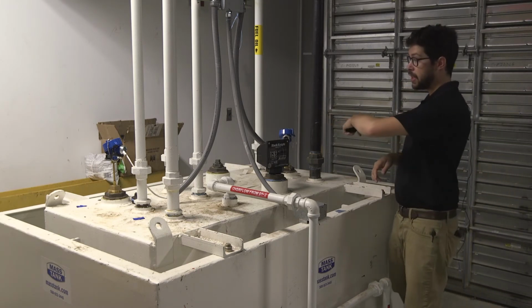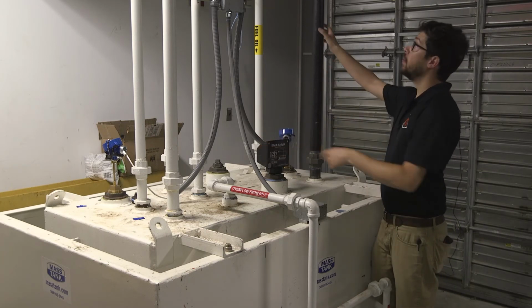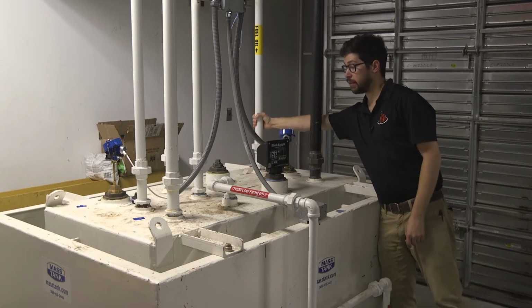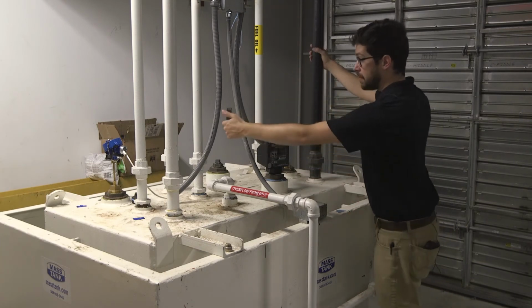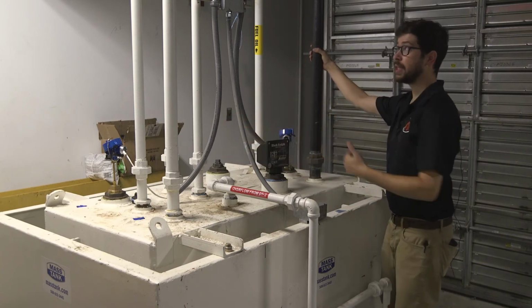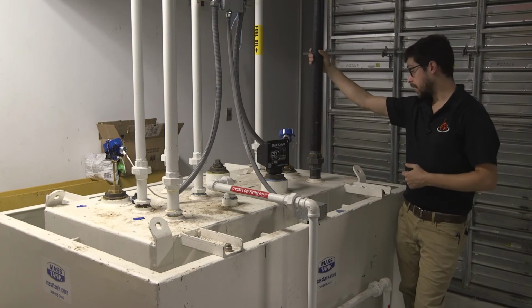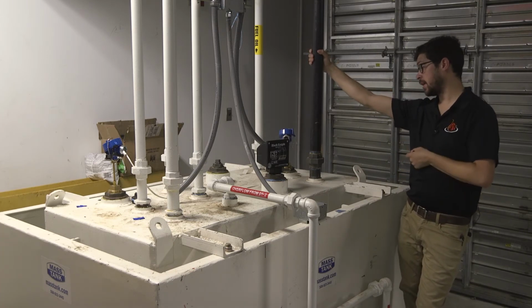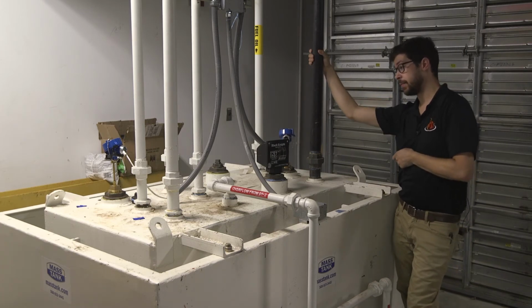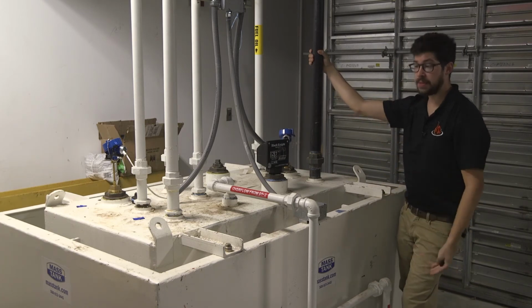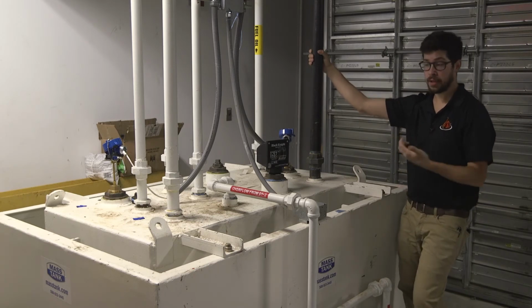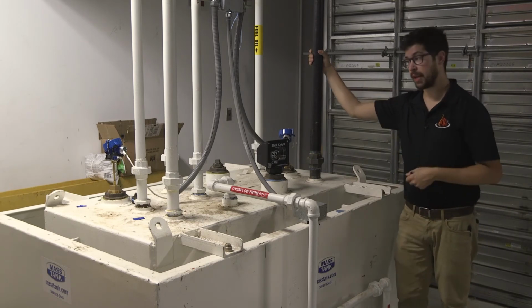Some of these connections here, these 5 pipes, this one in the back is your fuel oil fill, and then you have takeoffs and returns to each of the generators. This black pipe goes out to the roof, and it is the vent. Because obviously we're going to be filling and emptying this tank, we need some place for that air to go. If it was a sealed tank, we'd never get any oil in, we'd never get any oil out of it.